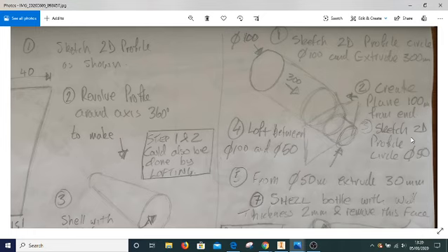What I then said, once we had put that 2D profile, step number 4 was to loft between the end of the 100mm diameter and the 50mm diameter circle that we just did, and it would create that tapered effect. So it tapers down from 100mm down to 50.